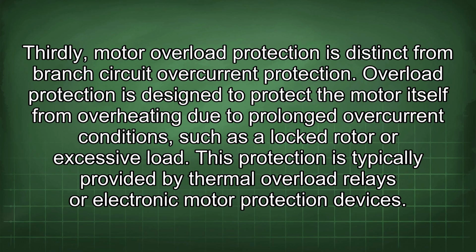Thirdly, motor overload protection is distinct from branch circuit overcurrent protection. Overload protection is designed to protect the motor itself from overheating due to prolonged overcurrent conditions, such as a locked rotor or excessive load. This protection is typically provided by thermal overload relays or electronic motor protection devices.